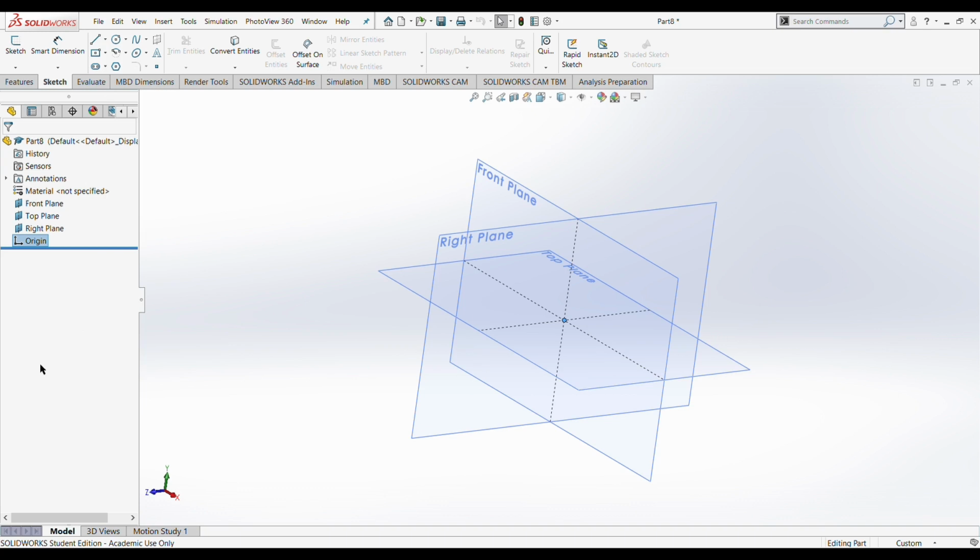Okay, right now we want to create a cube. Now we have to think about what the 2D version of a cube is. And that's kind of simple. It's a square. So to start off our cube, we want to first draw a square. The way we do that is that we select Sketch. Using Sketch will let you draw out your 2D object and let you turn that into your 3D object.